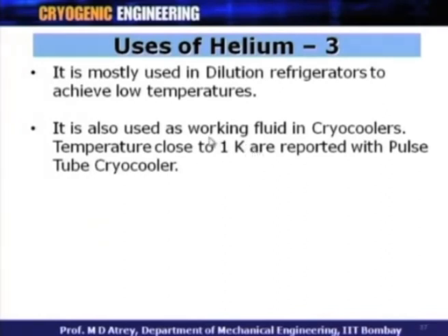But again, they also had to justify the usage of helium-3 in those devices, because the usage made the devices very costly, and commercially speaking, we do not have any refrigerator or cryocooler as of now which uses helium-3 as a working substance. However, most of the helium-3 requirement is in dilution refrigerators, which are very widely used in order to carry out experiments below 1 Kelvin temperature levels.